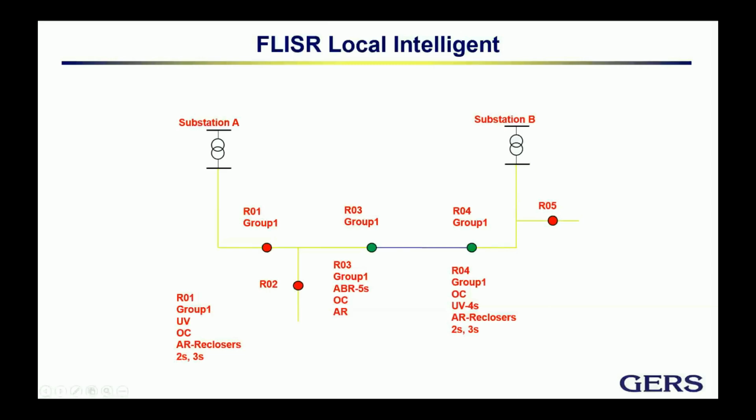As you can see, according to the setting there, it will count 5 seconds, closes, the fault remains, and guess what? It just opens. And then here we can do nothing else than wait for the crew service to come, fix the fault, and then bring the system back to the normal condition.